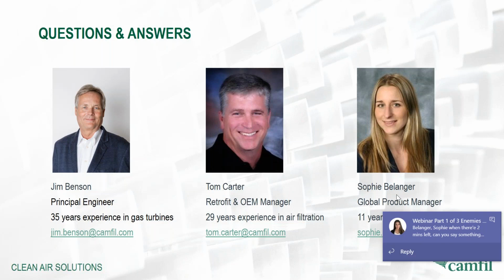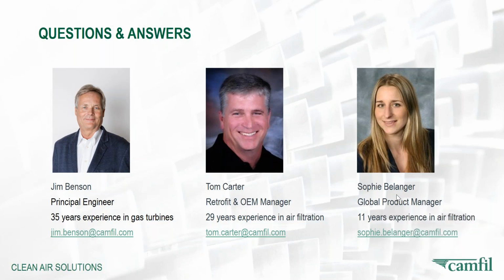Thank you. We don't have much time left, maybe one or two questions. There was something we haven't touched much, which is pulsing. So there was a comment about cleaning the filter through pulsing, and what would be the recommendation there in terms of pulse schedule as well. Well, let's start with this one. So where do we pulse, and at what recovery do we consider there's no more recovery and we should change the filter? A kind of complex question, and very much environment dependent.